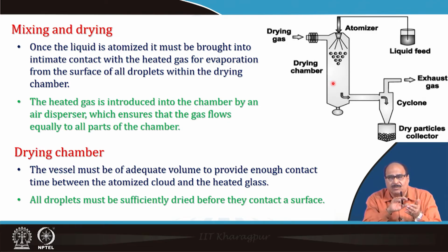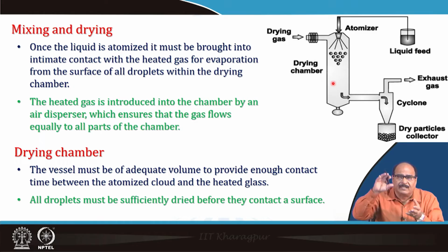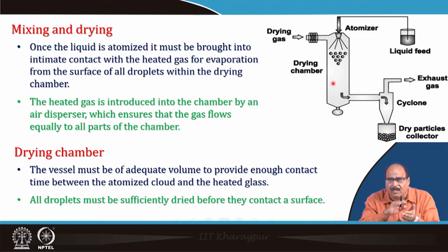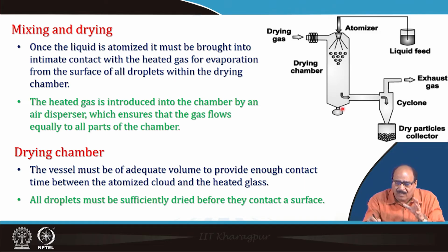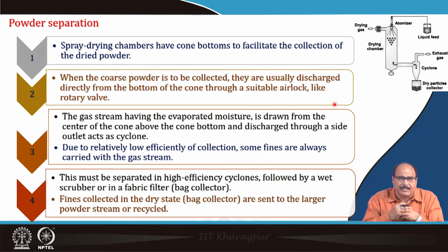They are heat sensitive, their Tg value, glass transition temperature value, is low. So, the material cannot be heated beyond a certain temperature; if it goes above its Tg, it will introduce stickiness, the product will become sticky, and its removal from the drying chamber will become difficult. So, a suitable modification may be that the drying chamber for such materials has to be a very high tower etc., or some other arrangements which I will discuss a little later.